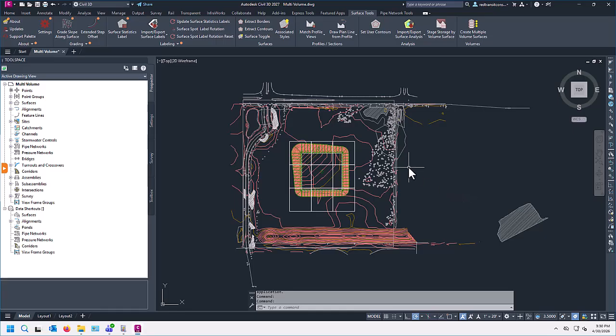Sometimes I'm working on a design, in this case a landfill, and I want to do volume surfaces of various sections of the landfill. Here I just have 9 boxes that represent those sections that I want to do volume surfaces on. But this could be for an entire site, and maybe you want to phase out areas. You could have these boundaries represent different phases of your site or whatnot.